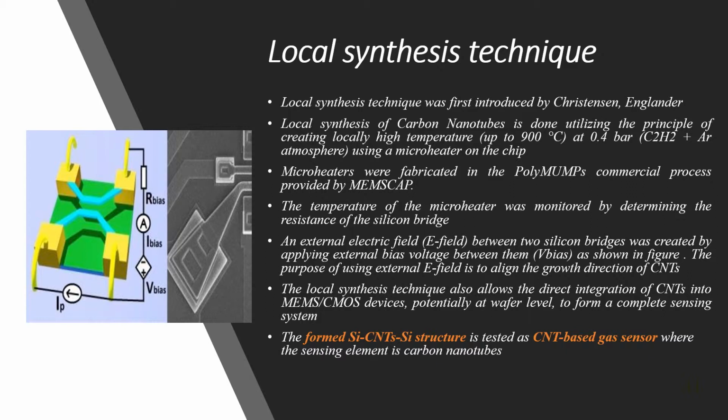Local synthesis technique was first introduced by Christian and Englander. Local synthesis of carbon nanotubes is done utilizing the principle of creating locally very high temperature, that is up to 900 degrees centigrade, at 0.4 bars of acetylene and argon atmosphere using a microheater on the chip.